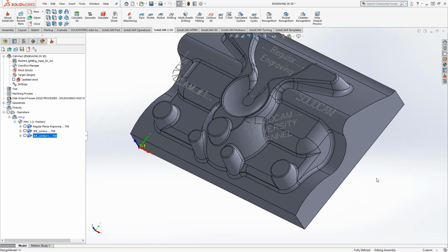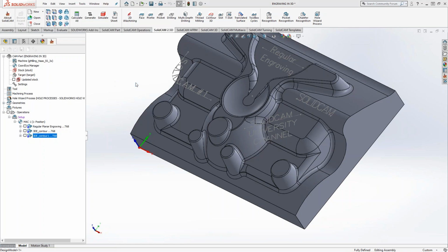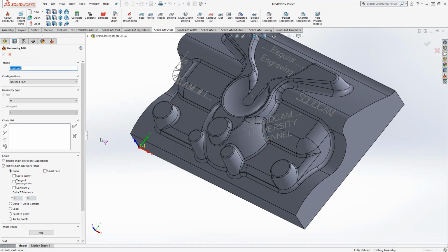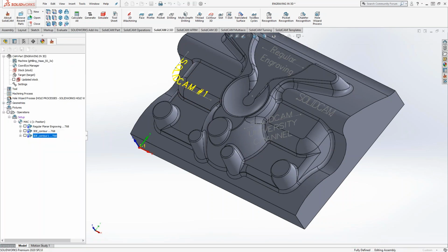Now, the cool thing with the engraving too, if you guys are thinking of questions, is this doesn't have to be, what I'll usually do is just pick a spot drill and use a spot drill for engraving part numbers. But if you guys are doing a lot of part numbers, they do make a tool specifically just for engraving. It's a little carbide tip insert that you can pull in and out. And if you guys are doing high volumes of engraving, that works very well.